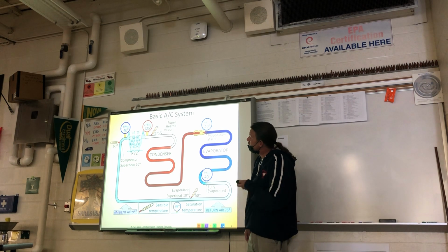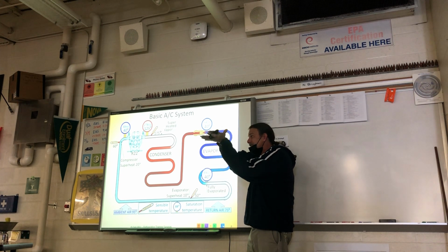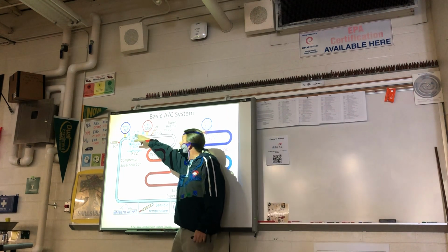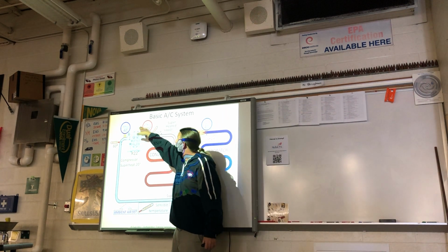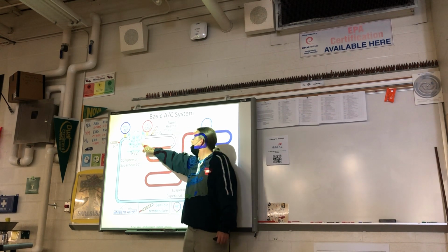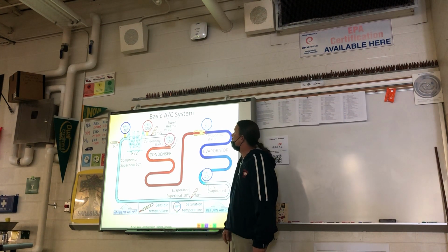Then once we go through the compressor, it's a superheated vapor, but because it got squeezed from this amount of volume inside a piston to this amount of volume, it really got hot. Pressure went way up, temperature goes way up. We almost go 4 times the amount of pressure between here to here, and the temperature goes up about 3 times. All right, so about 175 degrees coming out temperature-wise.